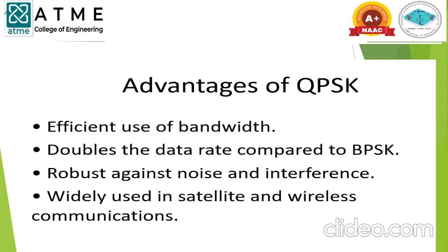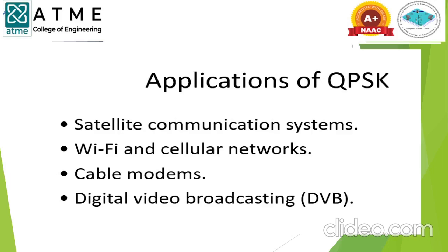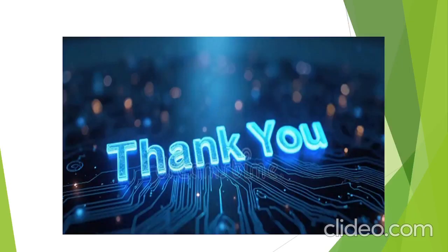Now the advantage of QPSK is that it is an efficient use of bandwidth. It doubles the data rate compared to BPSK. It is robust against noise and interference, and widely used in satellite and wireless communication. Applications include satellite communication systems, Wi-Fi and cellular systems, cable modems, digital video broadcasting and so on. Now we are going to simulate the QPSK waveform.